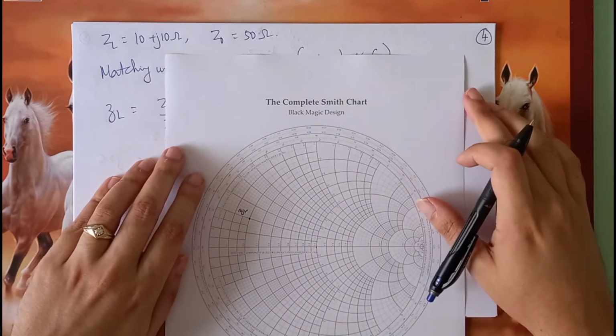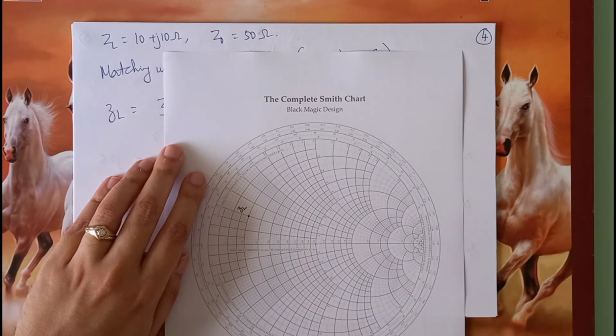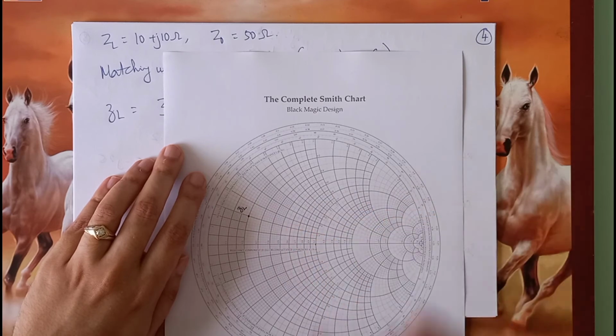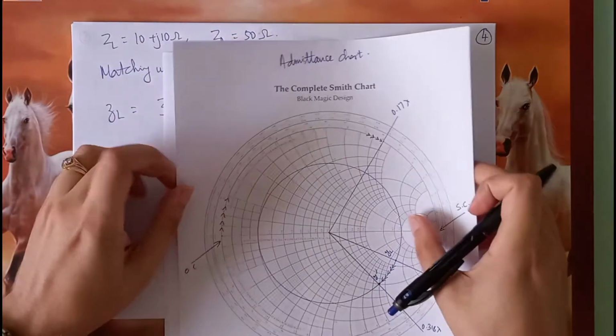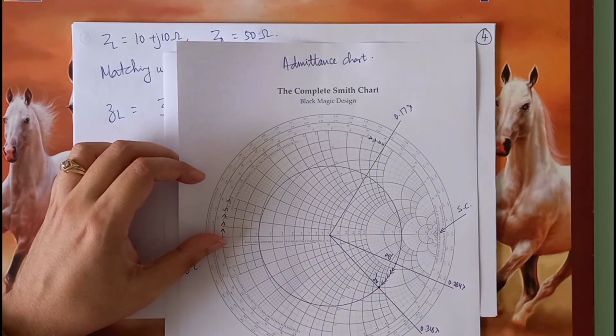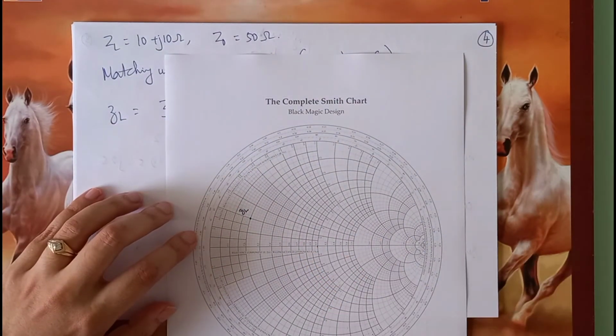So now, we can look at this matching problem as more of a pathfinding approach. That is, in the Smith chart, what are the paths which we can use to reach from ZL to Z0, which is the center of the Smith chart? Now, one way that you know is to have a transmission line. We draw the VSWR circle like what we drew over here. But the point is, if you move on the VSWR circle, we are always moving round and round. We will never reach the center. So therefore, we will just be making use of more and more length of transmission line, but we will never ever reach the center.